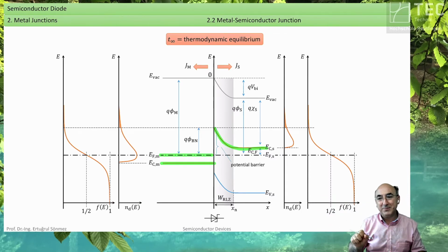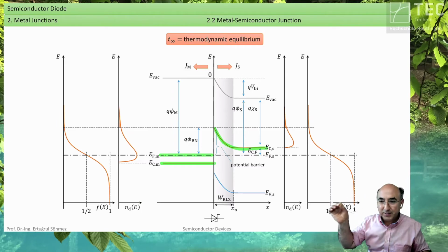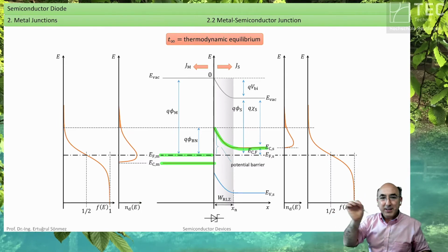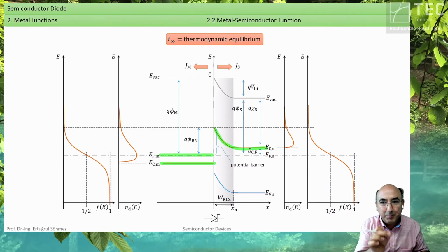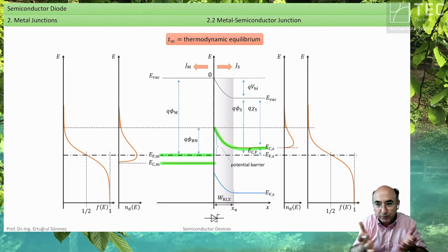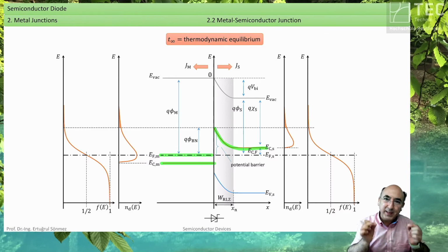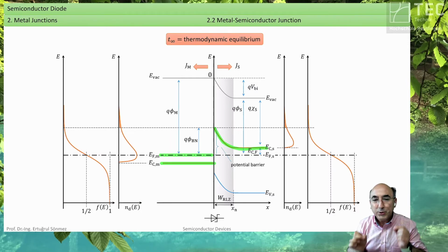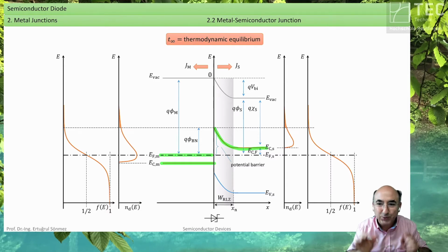In the neighboring facility, the particles in the environment have changed. Therefore, the conditions in the foundry changed a little bit, through all the filters which they usually, for sure, apply in the clean room. So all changes in the environment do affect the surface. Therefore, manufacturing semiconductors not only means controlling the environment in your lab, you have to control everything in your environment to keep everything constant.